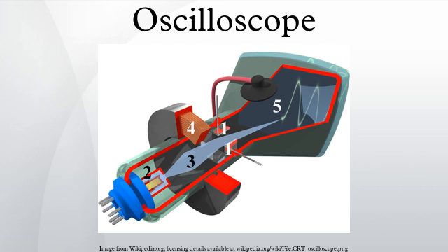Video trigger, a circuit that extracts synchronizing pulses from video formats such as PAL and NTSC and triggers the timebase on every line, a specified line, every field, or every frame. This circuit is typically found in a waveform monitor device, although some better oscilloscopes include this function.